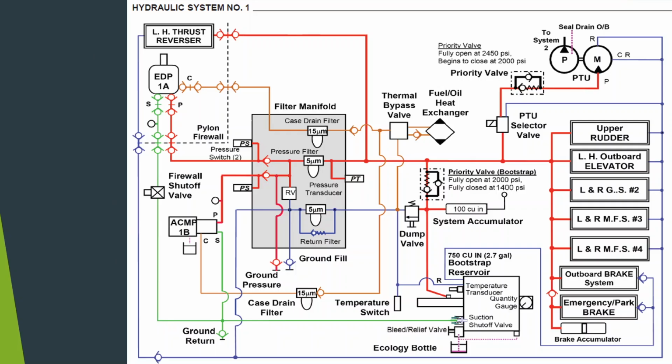If we look at these in a diagram of a system, here is a single thrust reverser system. This is the number 1 system off the Embraer 175. Lots of lines, right? But this one has a filter. They kind of put a lot of the filters into one module. They've got a couple separate filters, but there are some here.